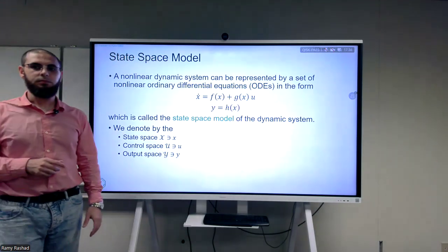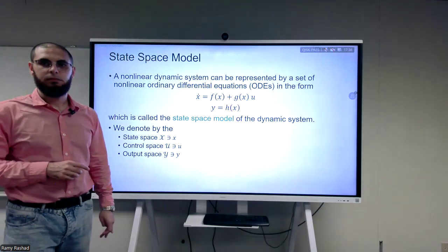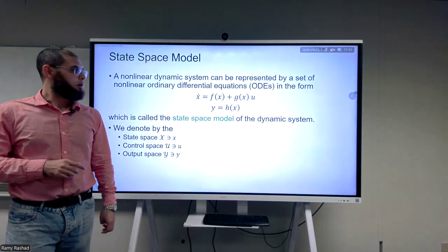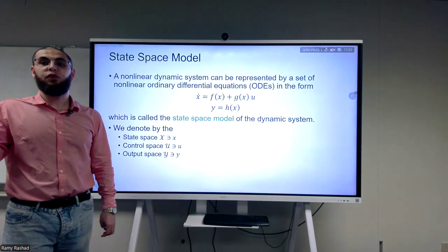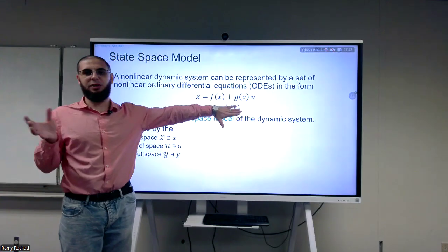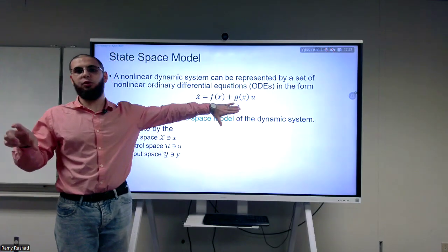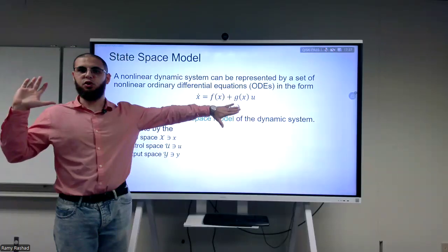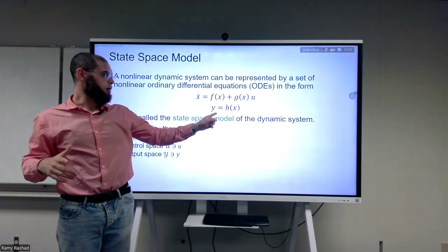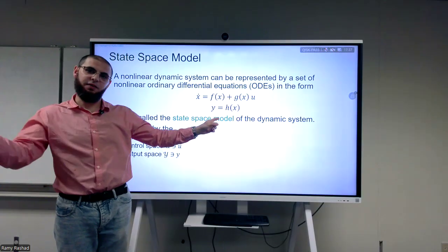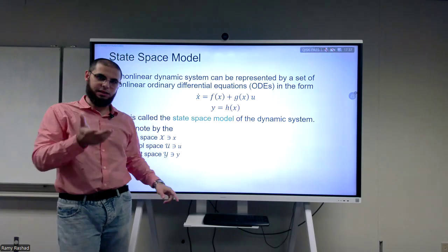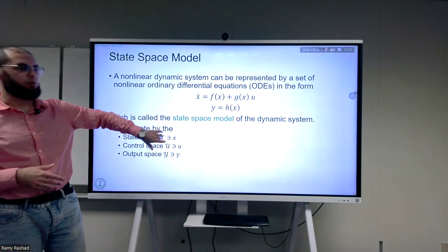Do we always have, in a mechanical system, that the input or the control is not affected by the output? This is after you do control, but for the dynamics itself, you don't have an output. If you're just looking at, for example, torques as an input for the robot, there are no sensors. We're just talking about you apply torques and the robot starts to move. So this is the first equation. The second equation says I have this kind of sensors that I want to feed back to design the controller. So that's another question. This is usually called the output equation.